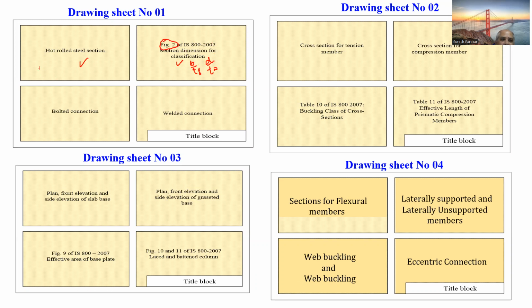We have seen now that the highest hot rolled section is ISWB 600, and we have this value something 4371, the Zp value, that is centimeter cube.